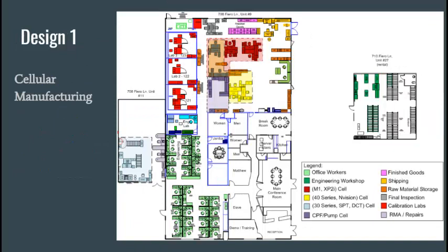Our first facility redesign incorporates our cellular manufacturing method. It can be noted that 4 cells identified in the cell matrix were grouped together as close as possible. Areas such as inspection, finished goods storage, and shipping were not taken into consideration since all product lines utilize these processes. It can also be noted that areas such as pre-welding as well as conversion and kitting tables are placed in between certain cells since they are both utilized by them. This design features 3 group cells in the main production floor and 1 in the auxiliary floor.